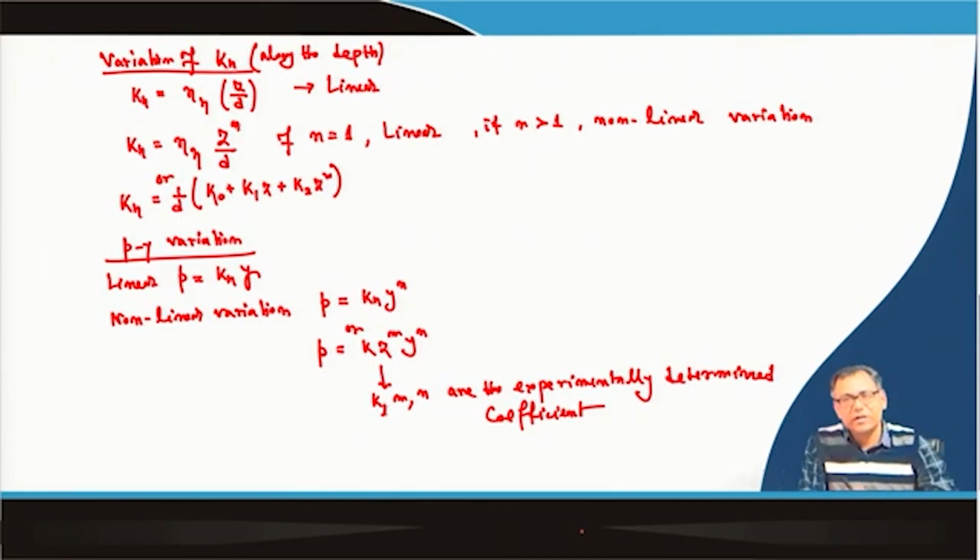Even this stress strain relationship, the load versus deformation relationship also changes along the depth. So, that also you can incorporate here, because as I mentioned, for different nodes you can put different variations.